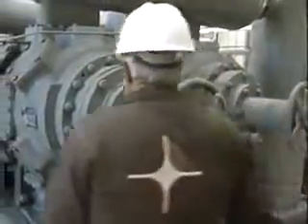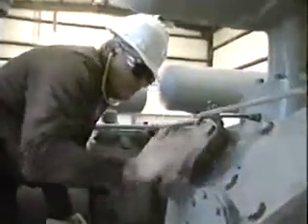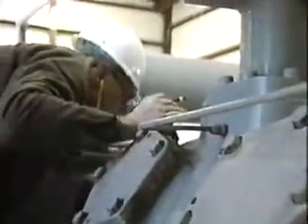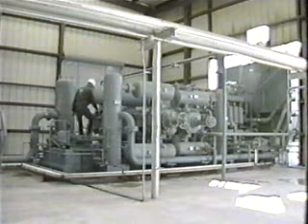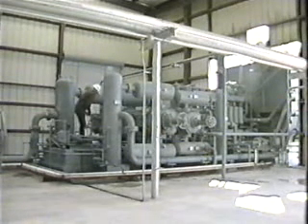Now check for gas leaks around the compressor, especially at valves, regulators, and the distance piece. If leaks are observed, schedule repair as quickly as possible because of the fire or explosion hazard. Be sure to inspect the mounting fittings for wear, tightness, and vibration.